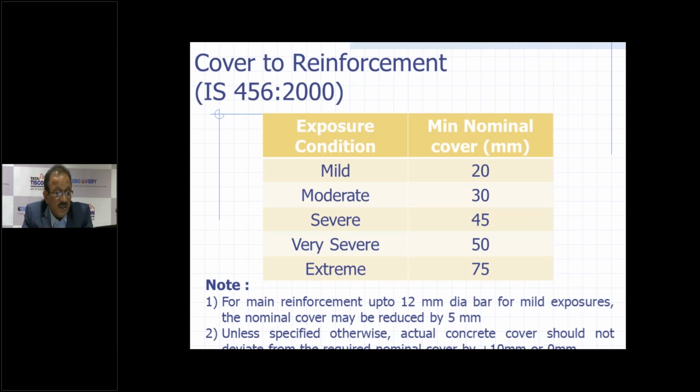And this cover plays a very important role, because at the end of the day, if the steel is not protected by giving proper cover, who is going to share the load? Concrete will only take care of the compression, but what about the tensile forces? If steel is going to be there intact inside the structure, then only the composite section is going to work and resist the forces.